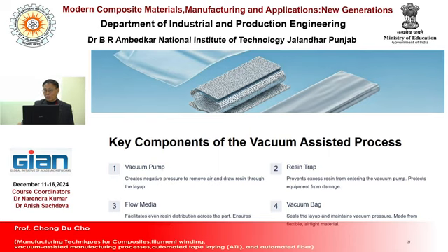A vacuum bag is needed. And the mold and layup preparation. Mold preparation for this technique: the mold must be clean. This mold is the lower mold, because there is no upper mold. So clean it and apply release agent.